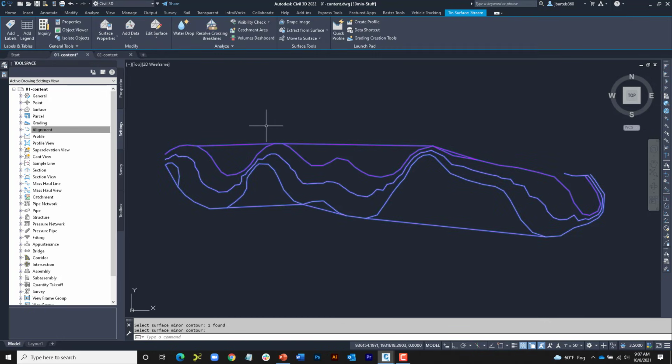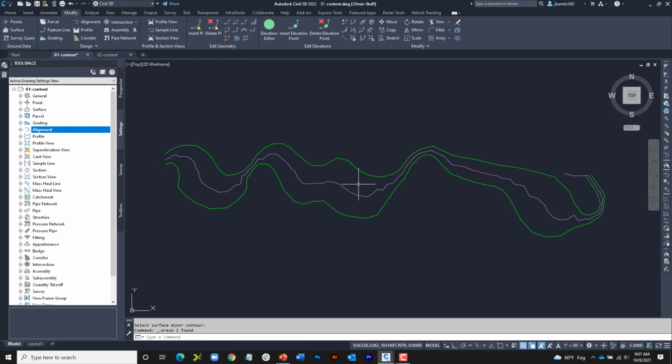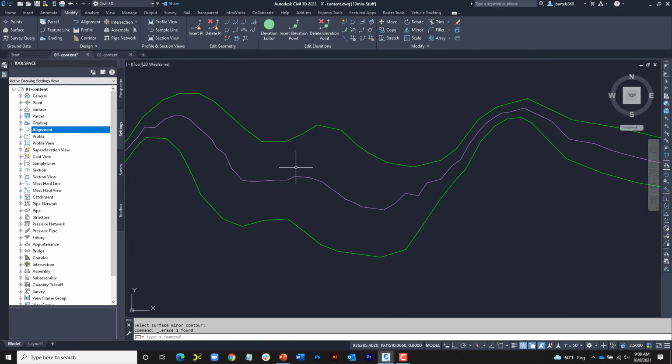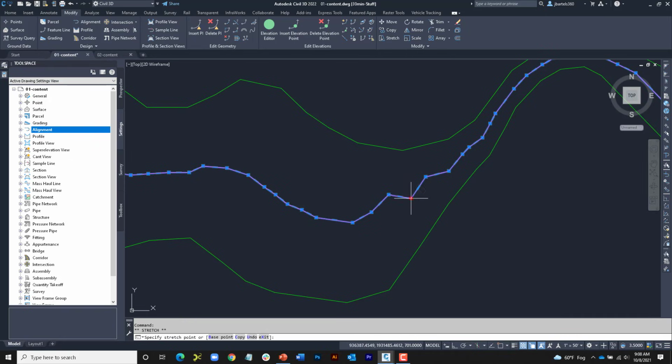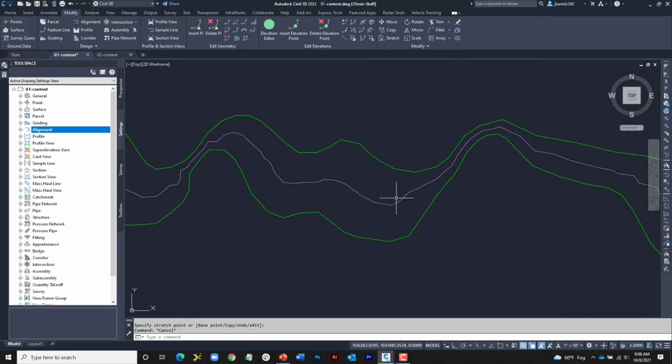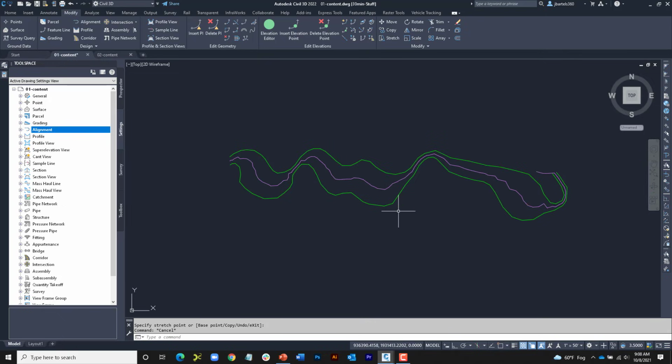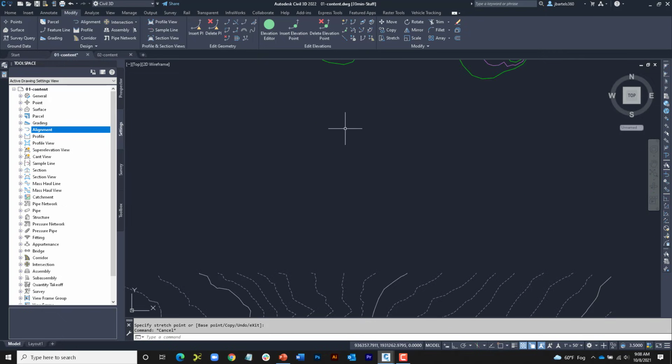That surface is still selected. I'll press delete because I no longer need it. And you can see I now have a polyline that represents the midline between these objects. Admittedly, it's not perfect. I could now turn around and use the best fit alignment through this entity to get me closer. Depending on how far off this is, I could also go through and make any necessary adjustments. So this is another way to find the midpoint between objects when you have complicated geometry.